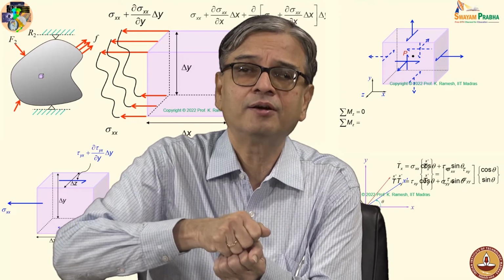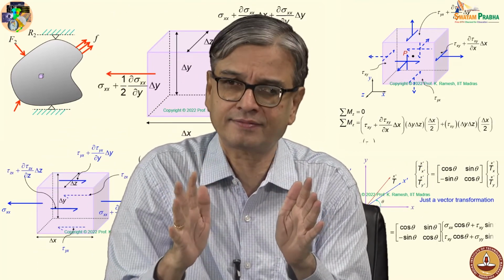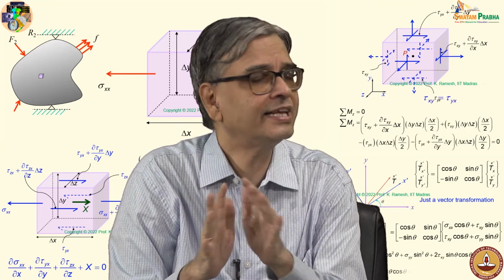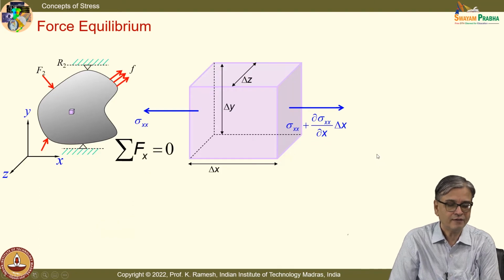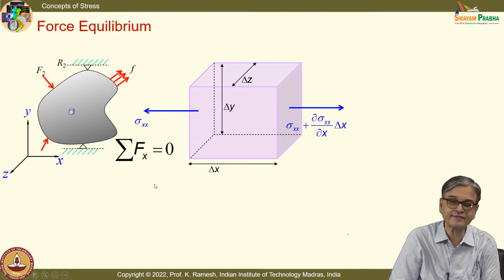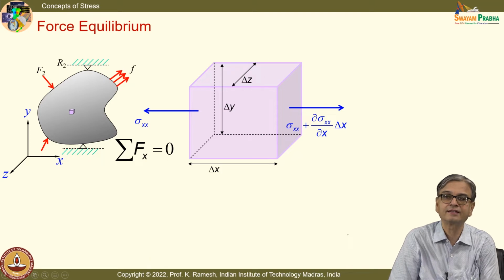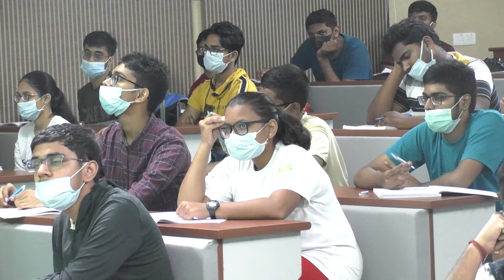When you take a simple tension specimen, it is going to remain constant. That is a special case. We are now discussing a generic situation. So following this, we would write and then evaluate what is sigma Fx equal to 0. And while I do this, I will write only components that will contribute to this equation on each of the faces. And you all know, if any of the shear stress components has the second subscript as x, that is what is going to cause it.